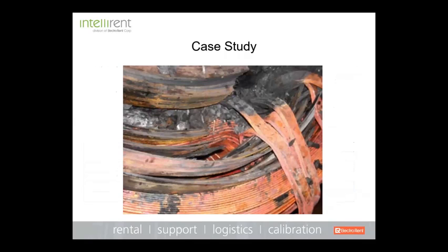So basically, when they tore the transformer down, you could see the dramatic effects of the mechanical failure. Now, let me just say this in terms of through fault monitoring and when to run tests and what tests to run.